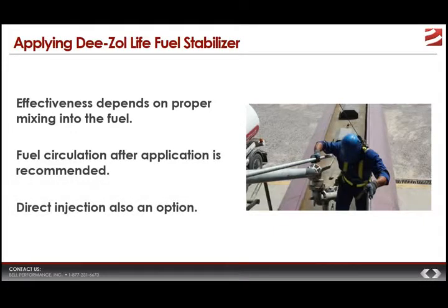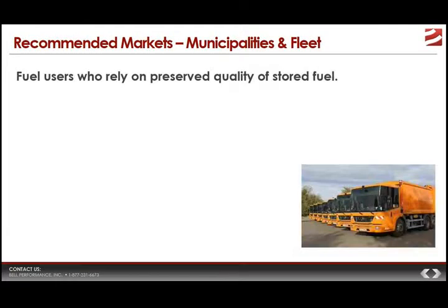You can also do direct injection. Now, a lot of people don't have this ability, but if it's someone who does bulk fuel storage, then many times they will inject the stabilizer into the fuel stream as they're adding additional fuel. That's another good way to get it mixed in.